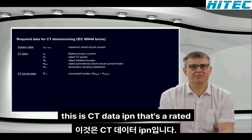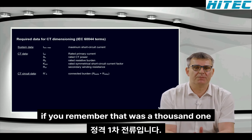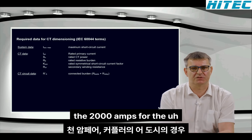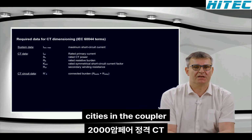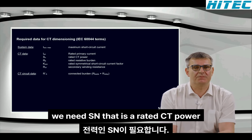The CT data: IPN, that's the rated primary current. If you remember, that was 1,000 amps for the feeder CTs and 2,000 amps for the CTs in the coupler. We need SN, that is the rated CT power.